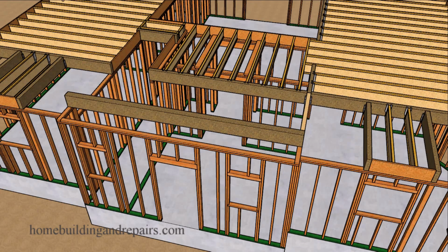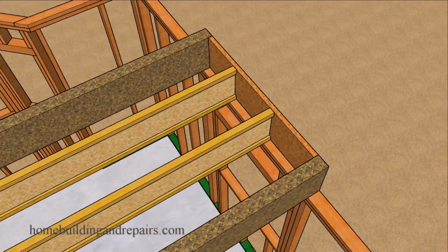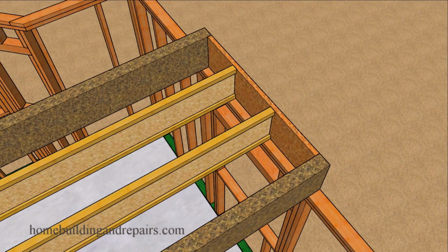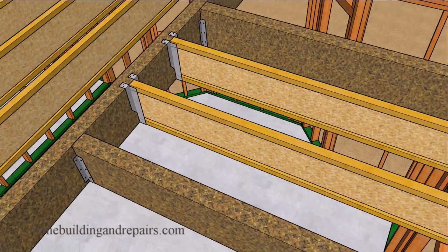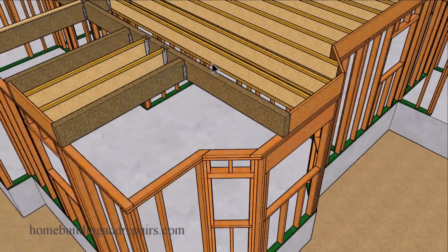And as you will notice going through the video, I don't think I have one beam that is not full bearing or sitting completely on top of the wall. Sometimes you will have the beam set back a little bit and then have the rim joist go through. And most of the time, either one of those methods will work for most engineers. And in this video, I will not be going over every single connection for the beams or the joist, because you can always contact the product manufacturer for that information or your engineer.